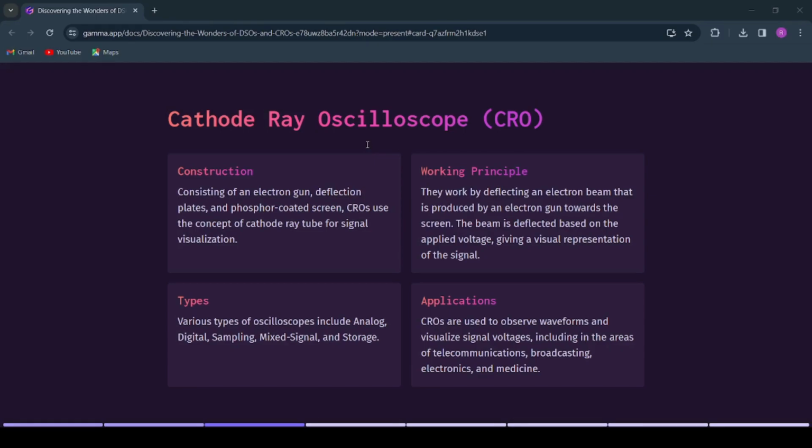Now we'll talk about the electron gun assembly. The electron gun emits the electrons and forms them into a beam. The electron gun mainly consists of a heater, cathode, a grid, a pre-accelerating anode, a focusing anode, and an accelerating anode. For gaining high emission of electrons at a moderate temperature, layers of barium and strontium are deposited on the end of the cathode.